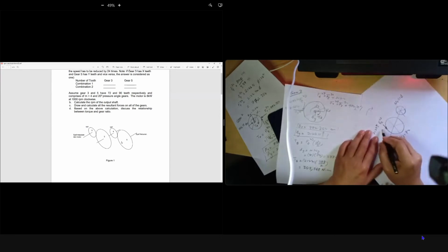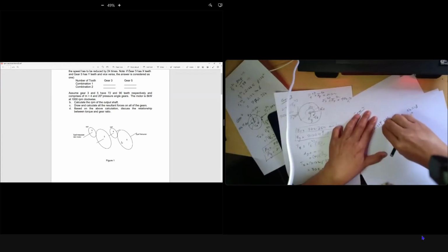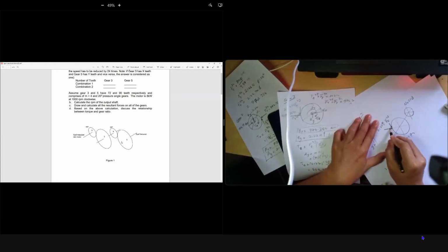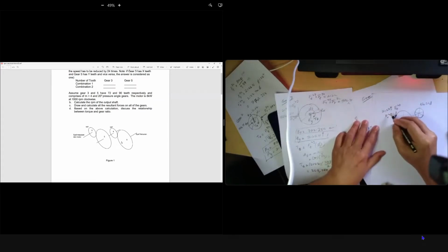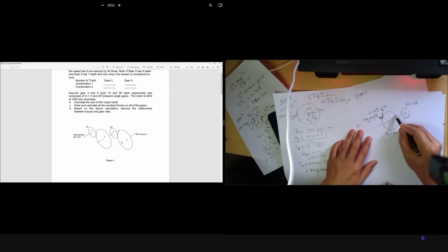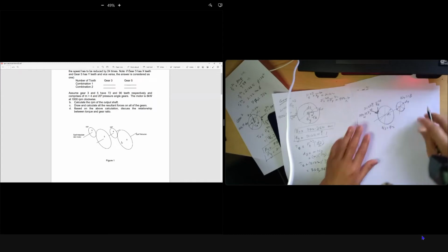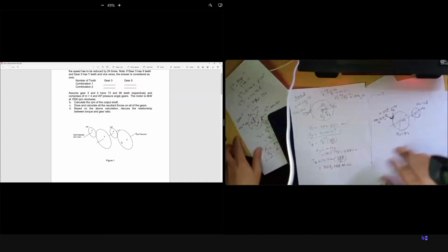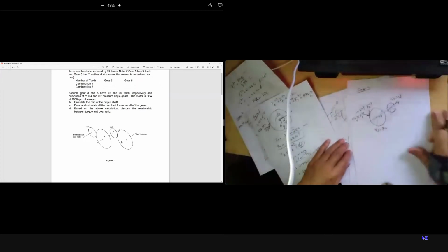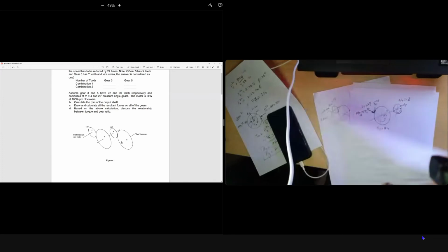And we have F radius in this direction, F radius 2 to 3, where the value is 772.35 Newton. This is your diameter 3, and we have N4 and this diameter 4. For the turning in your question, this one is clockwise, this one goes counterclockwise, this one also goes counterclockwise, the turning of your shaft is counterclockwise.